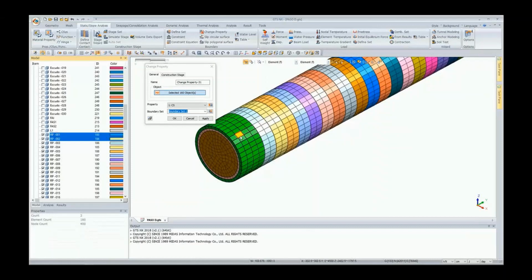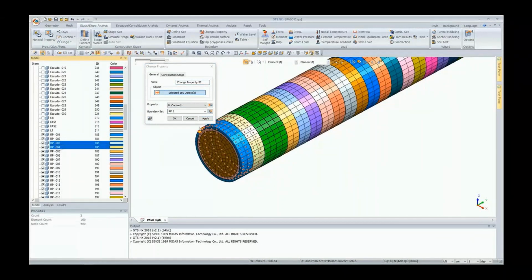And so we would be doing them in sequence. See here, I'm first selecting the first two supports, the primary support rings, and I'm changing that to concrete. And we see here now we have these icons showing that it now has a boundary condition for this new material. So I repeat this for the next two sets of rings, and I give this the primary support too, since these are going to be activated together.